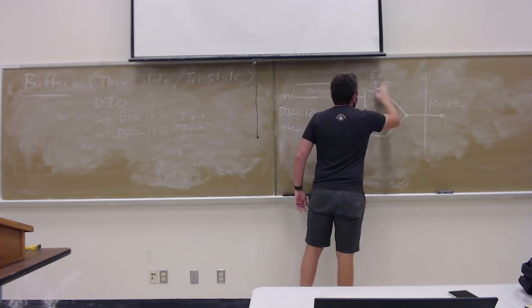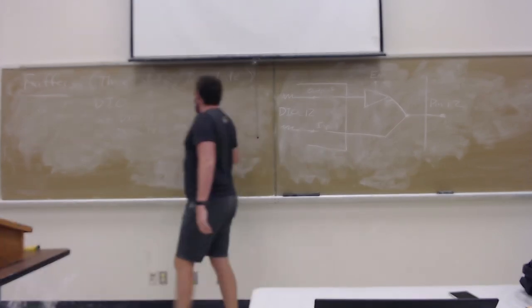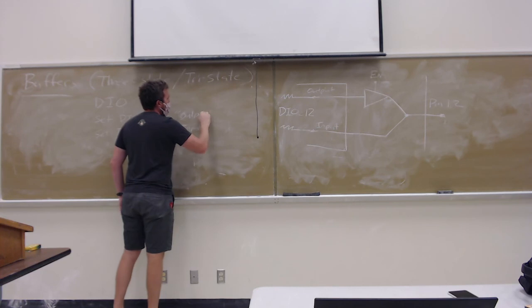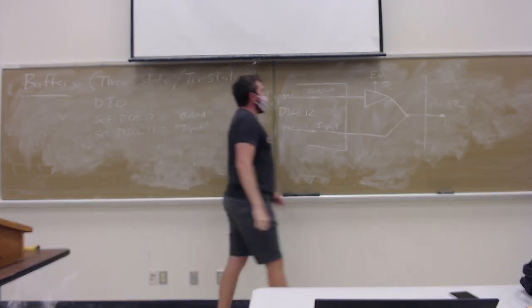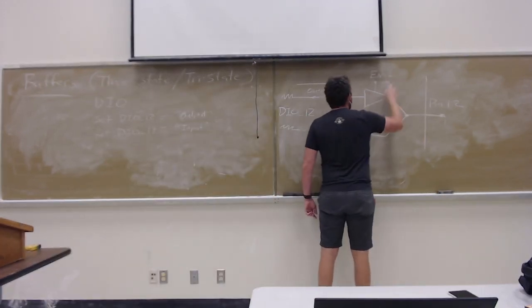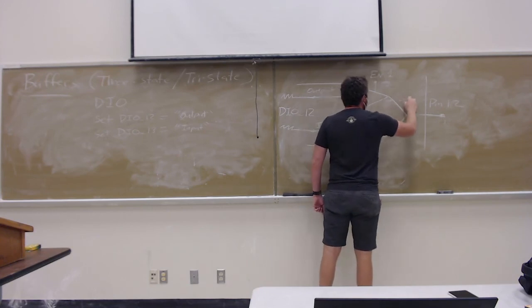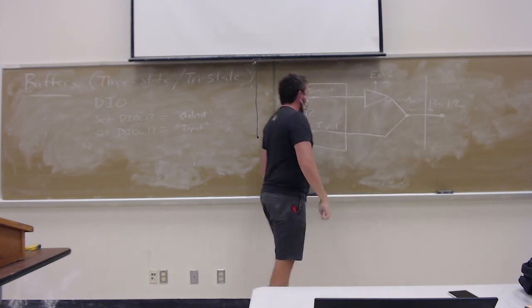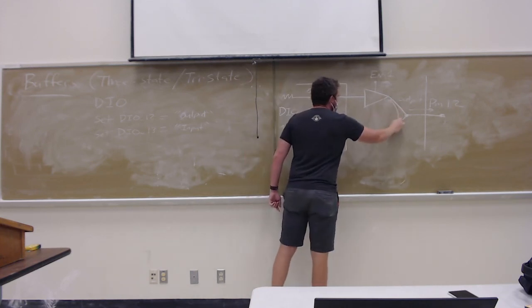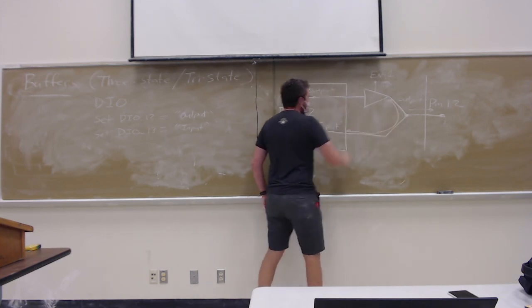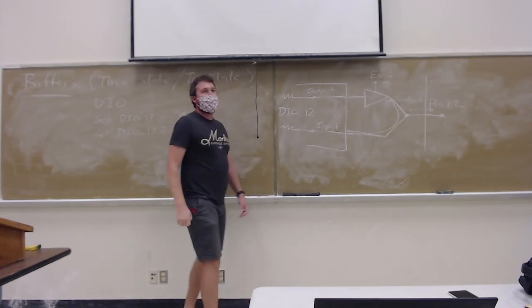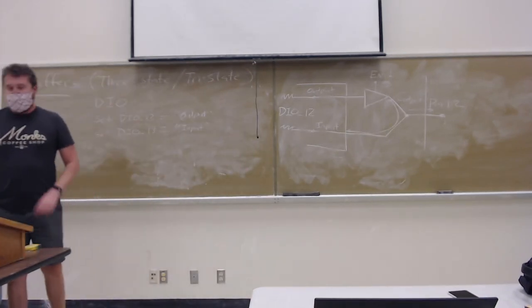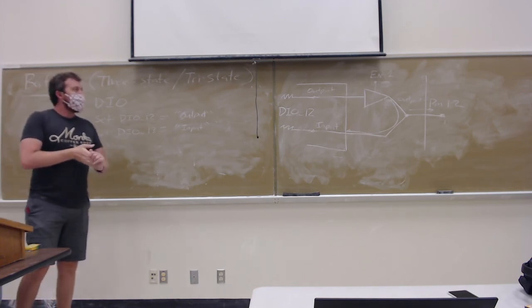But if then you turn around and set DIO to be an output, then it sets enable to 1, which means now we're passing the output out to the outside. Having the same output loop back around to the input is not that big a deal, because we're not doing anything with it anyway, since we've already said that pin is an output pin.